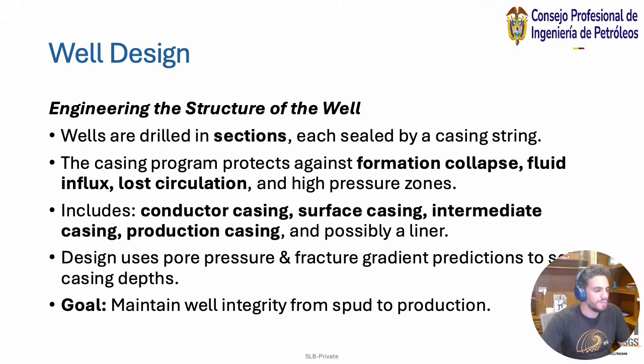So when I'm drilling, this high rotation or high torque, the pressure I'm applying, and the depth I'm going, what they call rate of penetration, it gets very hot. When it gets very hot, the mud around it loosens up, and you have to circulate that mud out.